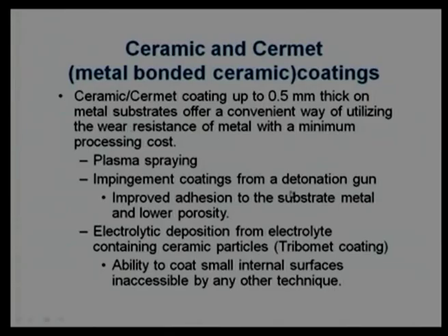When coming to the detonation gun, we use high velocity to impart kinetic energy to the surface and give some sort of penetration or diffusion mechanism, so that coating remains in contact with the material which requires coating. Plasma spray is generally a high temperature coating. It is an easier one to deposit at high temperature and then cure it,